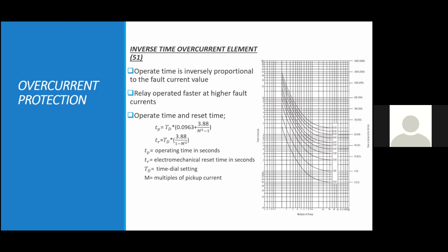So that's where the name inverse time overcurrent element is derived from. And I've also shown an equation which gives you the operate time and reset time. One thing to note here is there is no electromechanical reset in this relay, but we can simulate that electromechanical reset time by using this equation.